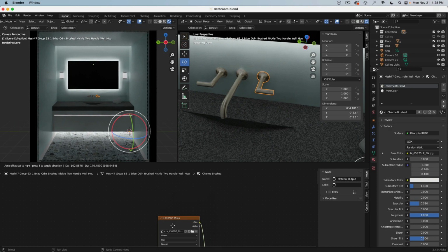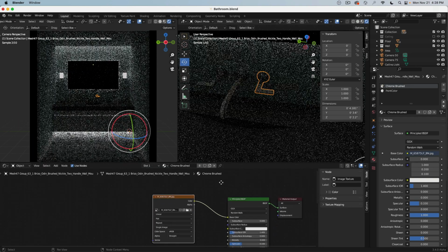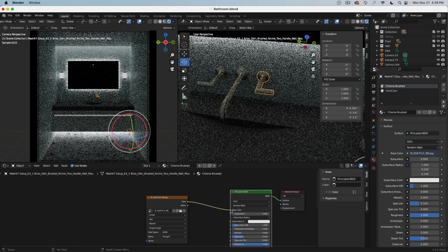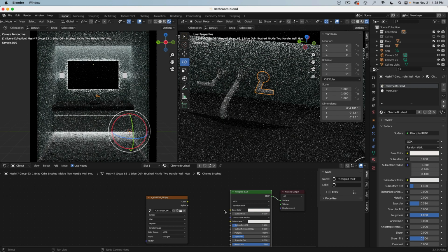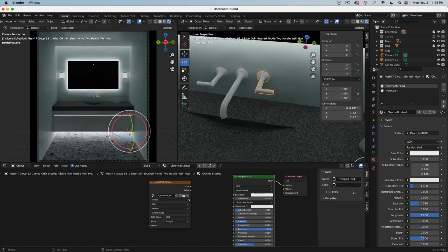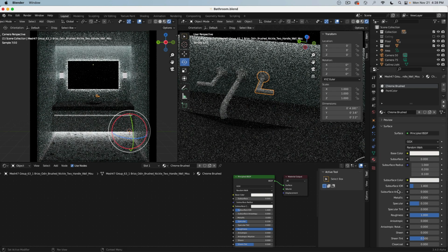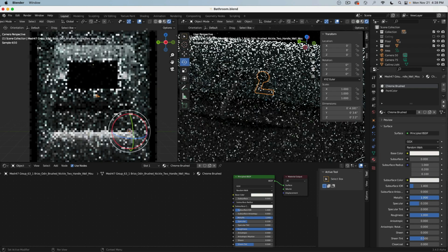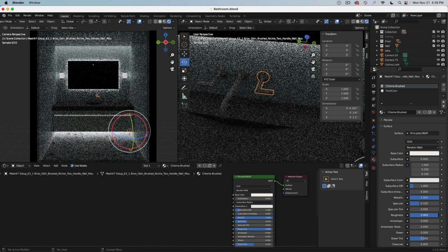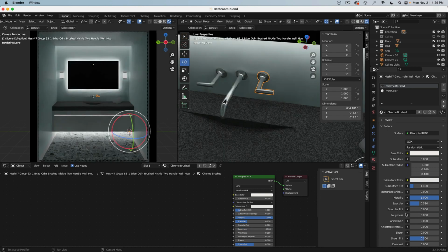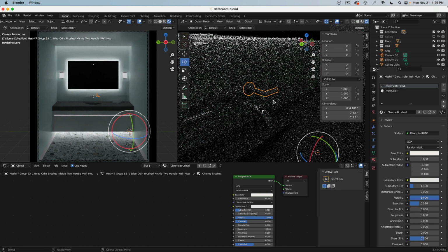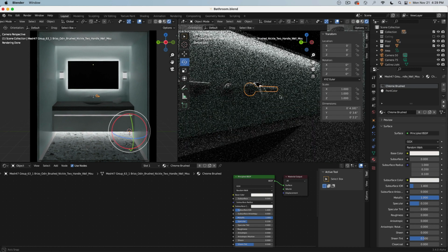And then here is this texture image that's being used to show up in the reflection. And when I drag this out, you see this reflection is gone. This whole thing I can select and delete. And then this is metal. So let's make this metallic. Roughness down. Oh, look at that. It's reflective, and it really reflects the environment correctly. It's not a fake reflection.